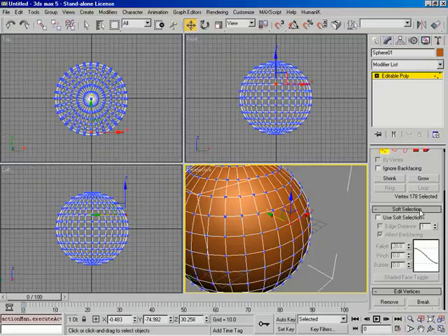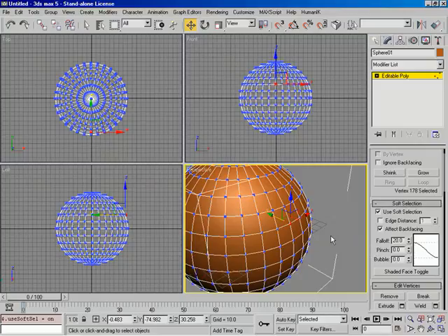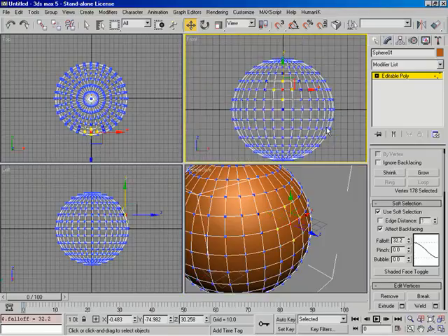First thing, what I need to do is simply turn on Use Soft Selection. Right now, we're not seeing anything special going on because my fall-off is too low. So I'm going to start increasing my fall-off, and as I do, look what's happening. Oh, so what's going on, Zach? What are you seeing? Getting a gradient effect moving from red to orange to yellow. Exactly. And then it fades off, and once we get all the way out to blue, blue's just not affected.